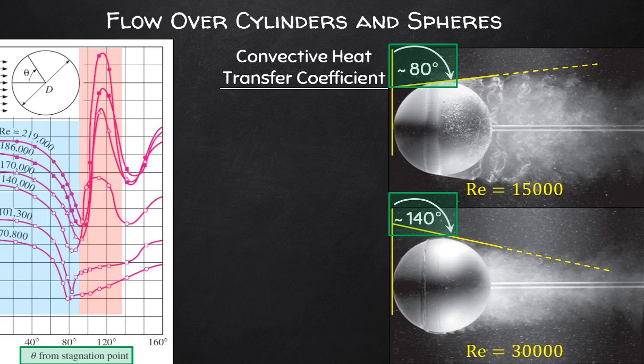Okay, so for low Reynolds numbers, the Nusselt number decreases and then does so quite sharply at specific Reynolds numbers, while for very high Reynolds numbers, the Nusselt number will first decrease, okay, and then you'll have this very sharp increase, and then there will be a kind of recovery.